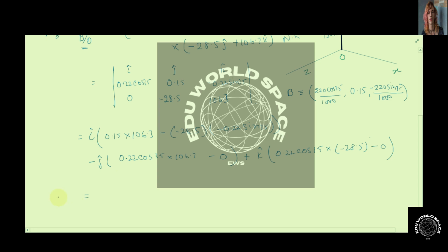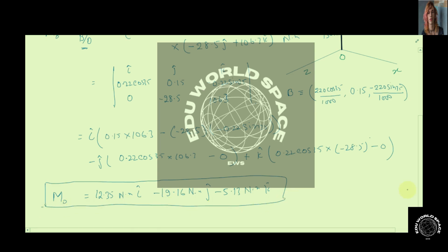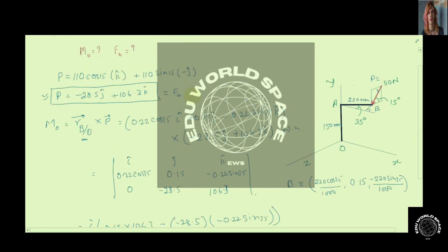If we solve this using a calculator, the moment about O comes out to be 12.35 Newton meter i cap minus 19.16 Newton meter j cap minus 5.13 Newton meter k cap. So this is the equivalent moment about point O for this system, and the equivalent force at point O we have already calculated. So this is the final answer.